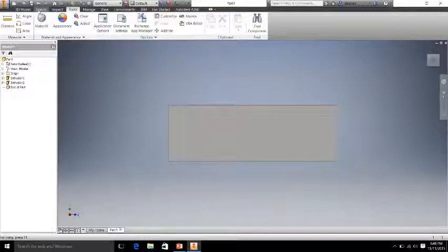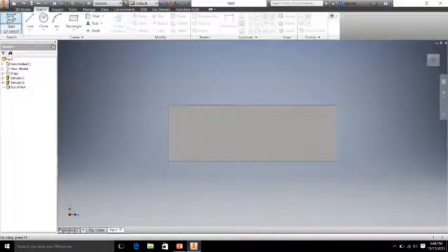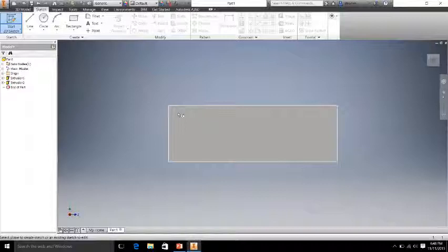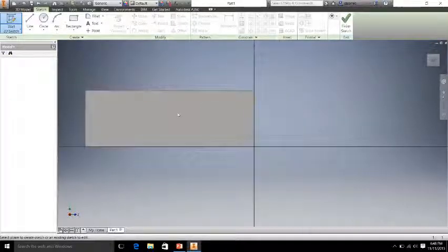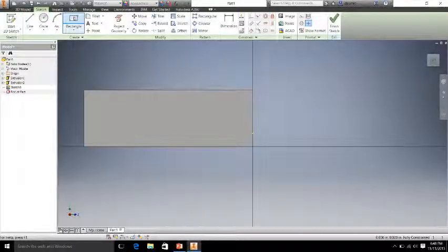So if we come back up to the top, we hit sketch, we create a 2D sketch. I'm going to select that left face. We're going to create another rectangle on top of it. So I'm going to make sure, note that there's a little blue check that happens when I get right in the corner. That's what we want to see. I'm going to drag down. Now we know if we go flush with the bottom, we're going to be at 0.75. That right dimension says 0.75 once we click to the bottom.